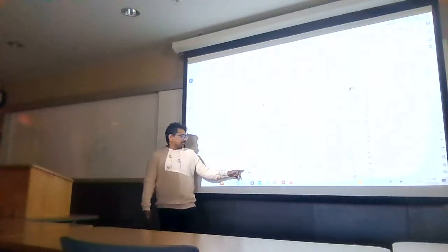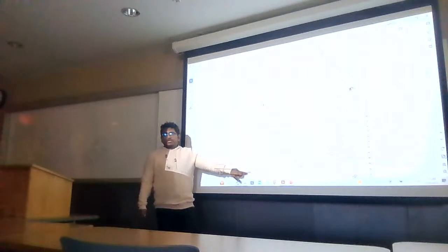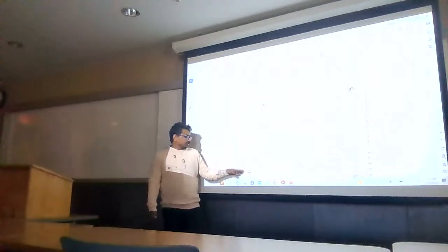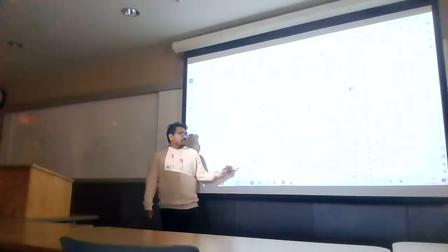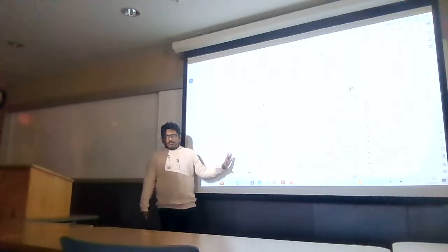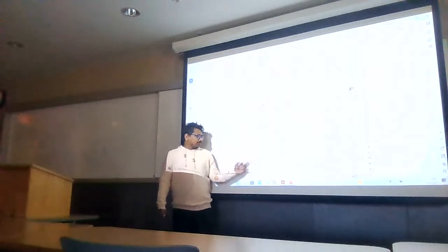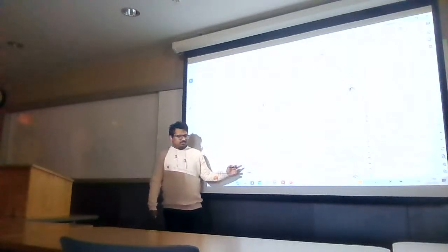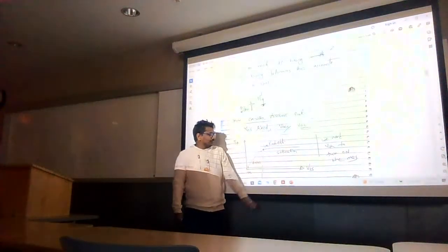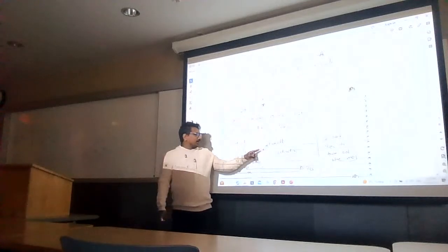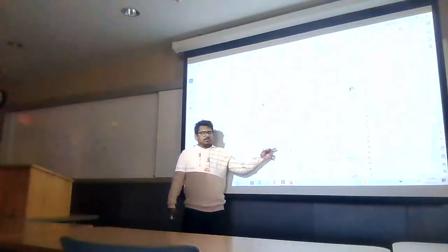However, there is another point which is known as threshold voltage. My transistor will turn off before this threshold voltage. Let's say this threshold voltage is 100 millivolt, and if I apply 90 millivolt at the gate, still this transistor will be off. It works like a switch, an off switch. However, in this linear mode, my transistor works like a resistance. But we do not prefer this region. We are interested in there. First of all, to design an amplifier, my transistor operating point should be there.